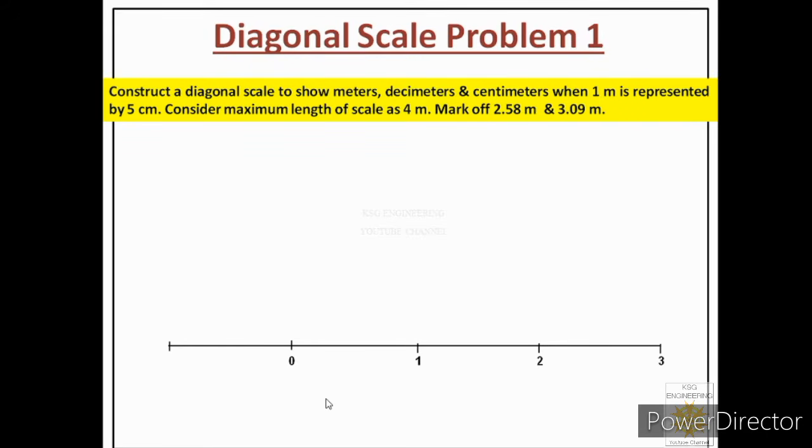Now let us label the units. Now which scale is this? This is a meter scale because these 3 divisions are representing 3 meters. So what we will do next, we will draw 2 guidelines and take the gap between these 2 guidelines around 5 millimeters or 7 millimeters and use Gothic letters to write meters in capitals.